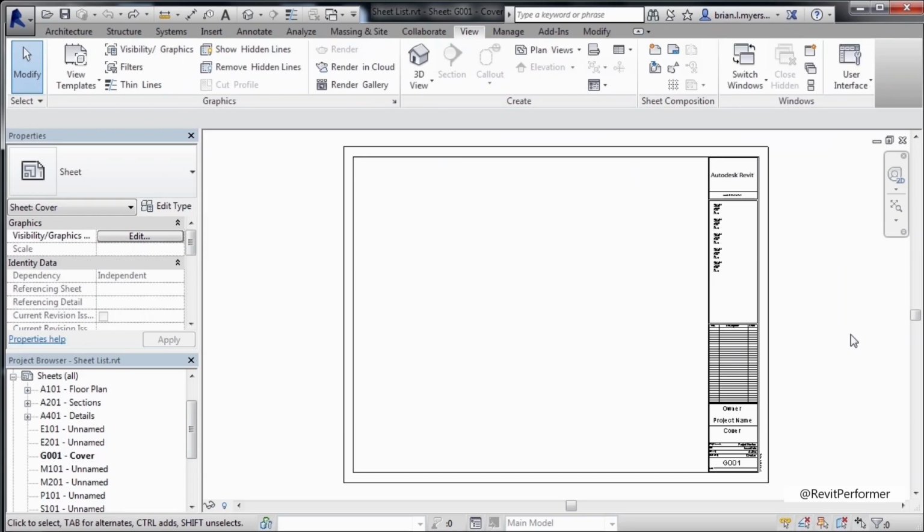A sheet list is very much like a table of contents in a book. When you have a sheet list created, you usually include it in the set to make things easier to find inside of your set of construction documents. In the sheet list, you'll see a listing of every sheet and the information associated with those sheets. Also, you'll get to see the order in which those sheets are included in your set of construction documents.